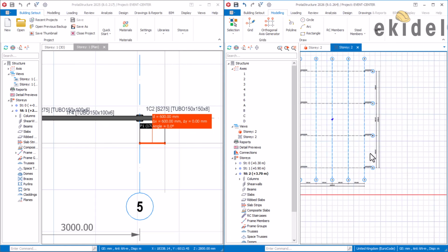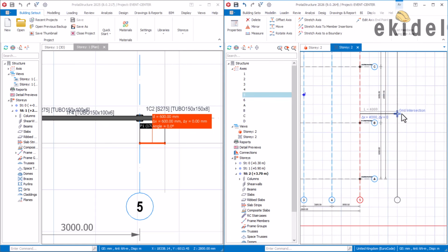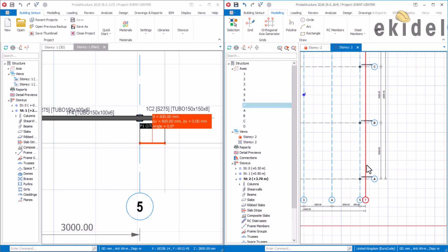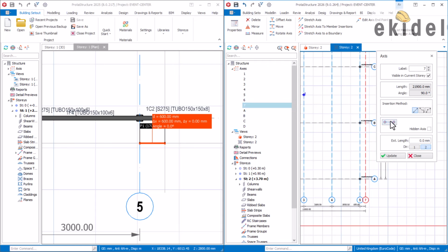Then I will do the same thing here, click here, right click here, and then offset forward, function F2 key, and then 600 positive because it's going in that direction. Then double click on this one, and that opens up. Come here, hidden, hidden, hidden. I like to make it hidden because these are not major grid lines, so make it hidden.